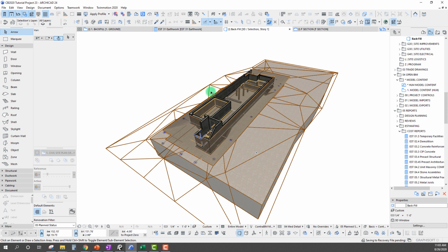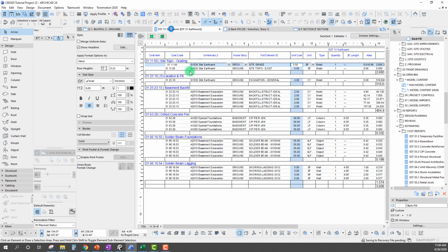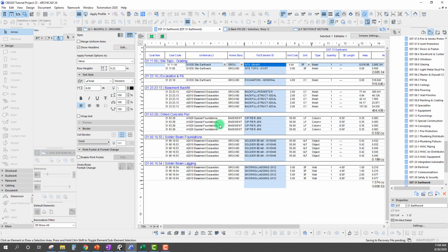In this case, that would be actually a good element to use as a kind of general fine grading. So we can throw maybe 50 cents a square foot or something in that range at it. We can see our total area here. So this would account for fine grading at the subgrade as well as on the site for any fine grade adjustments there.